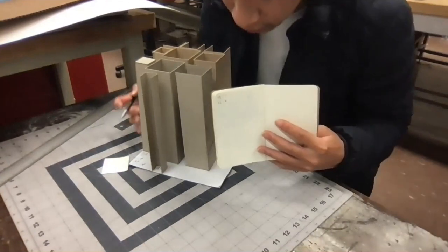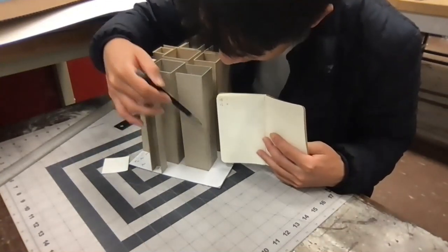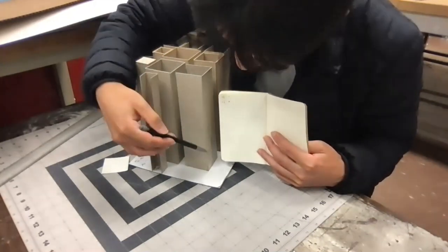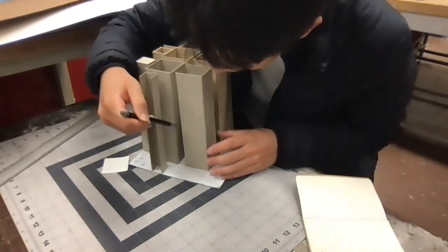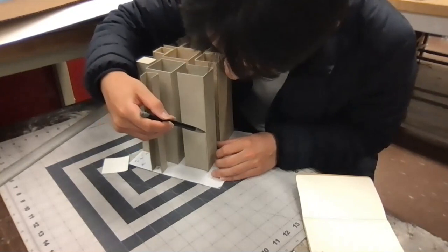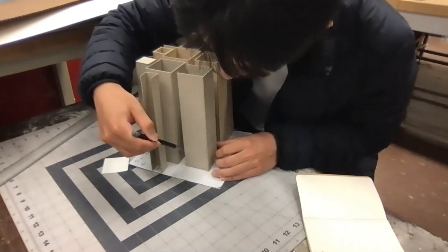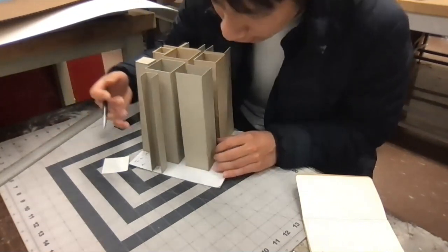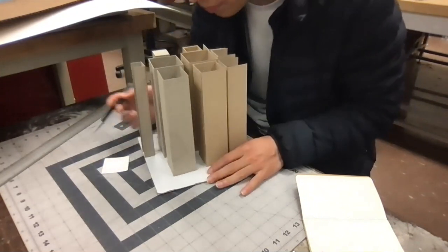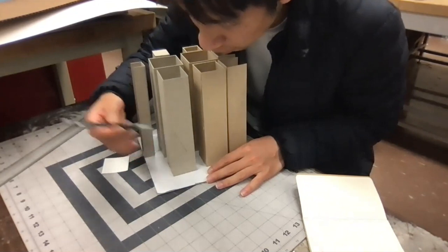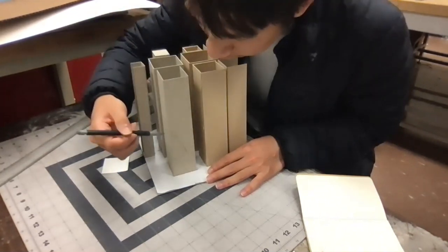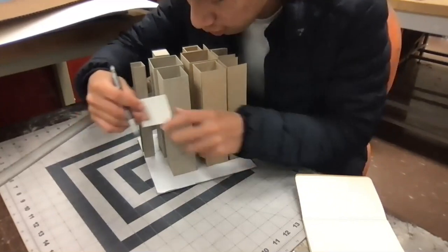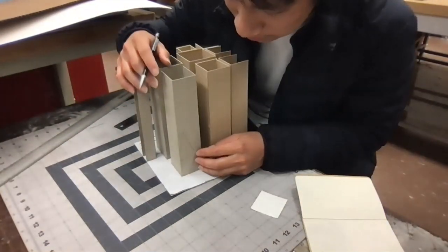So I noted in my sketchbook that this top part comes from the top to this point at 4 and 5/16 of an inch, and this bottom point at 6 and 7/16 of an inch. And so I marked those points on here and here, and then I connected these lines going towards the back as it is going to be extruded to the back, right? And so in that way, we'll be cutting out, or we'll be subtracting from this column the area where the square intersects as it goes back towards this column. And then, yeah, we're just cutting out.